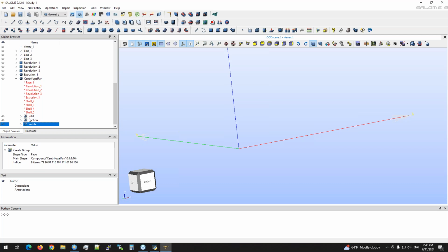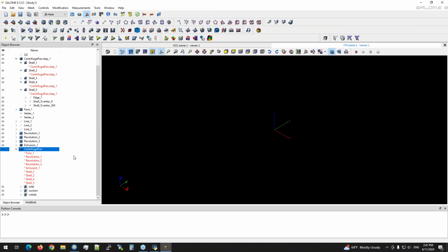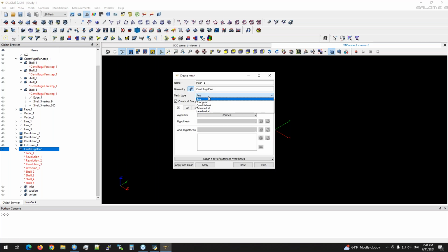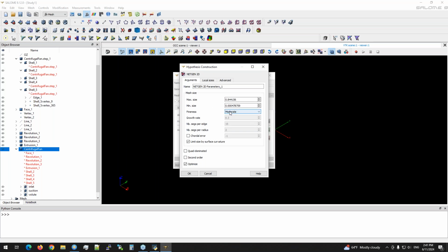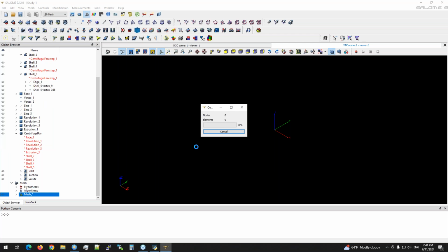So as an example, in advance I have exported it and created all the parts for our next step of setting the mesh parameters. And then here there is a module for discretization, for meshing, for example, the 2D surfaces. So I can click here, I can create the triangulation by Netgen typically. Here you can set the meshing parameters, so the sizing of the triangles. So let me set some rough estimate for the sizing. So 1 millimeter as a minimum, for example. Now we can apply this, and I can run the triangulation just to show you how it works.